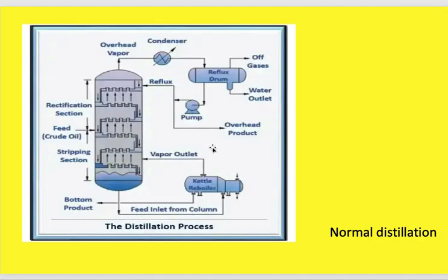Look here at this tower. For any normal distillation tower, we have two parts: below the feed entry and above the feed entry. At the bottom here, we have the stripping section, which is famous. If we did not add this reboiler, you would find a small number of theoretical trays, but by adding a reboiler, you add additional theoretical trays. We make vaporization, add Q to the bottom below the feed entry, and let the vapor go back to the distillation column. This makes the distillation more efficient.